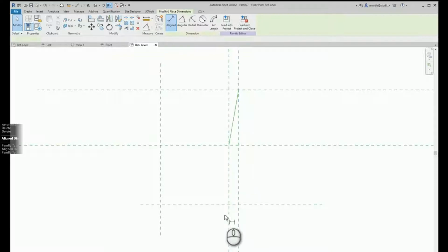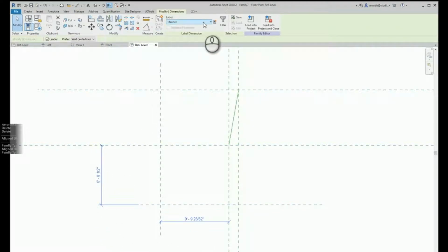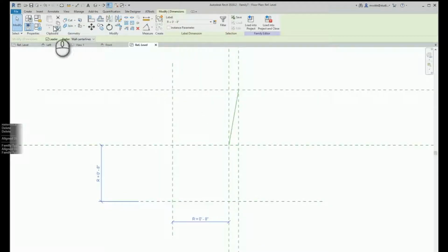So I'm going to create another dimension here and another dimension here, and both of these dimensions are going to have a value of r. Now we're going to come back in here, and I want you to take a look. We haven't changed the location of this reference line or these two reference planes. We've just deleted those earlier dimensions of X component and Y component. What I'm going to do to that X component value and that Y component value is simply add an r to it, and then reference those same X component and Y components off of these two lines now, instead of the two reference lines that go through the origin.